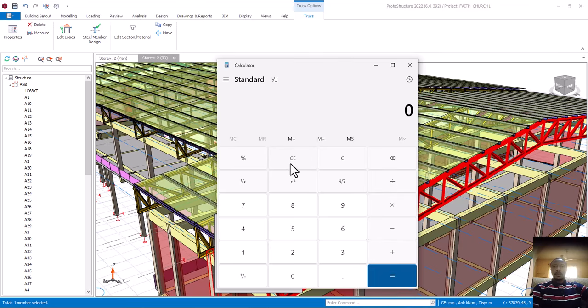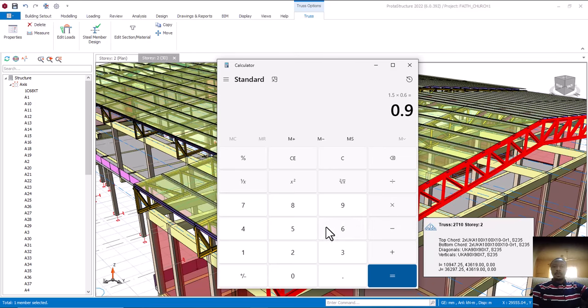So let's cancel it. Now come to our live load. Live load has a factor of 1.5. If it's a BS code we are using, that's 1.6 live load and 1.4 dead load. Is that okay? But we are using Eurocode. So therefore multiply by 0.6, then you give us what? Give us 0.9. Am I correct? 0.9, isn't it?